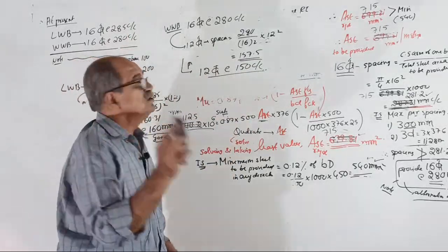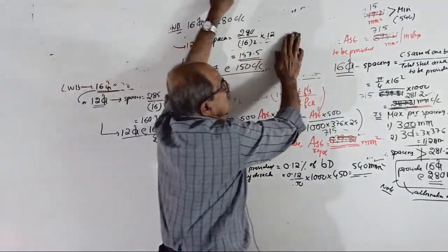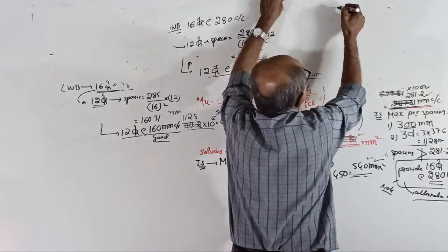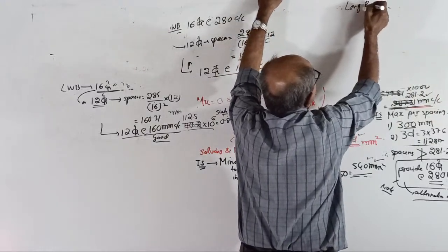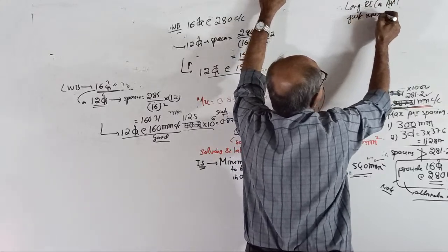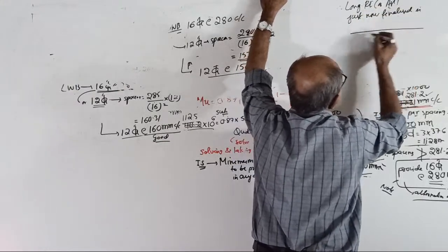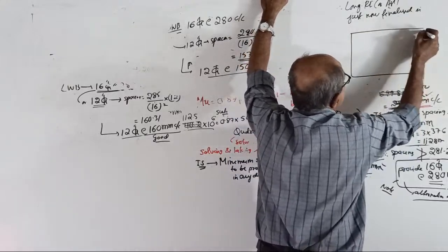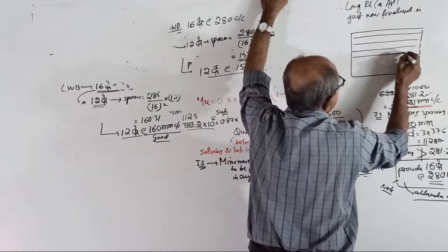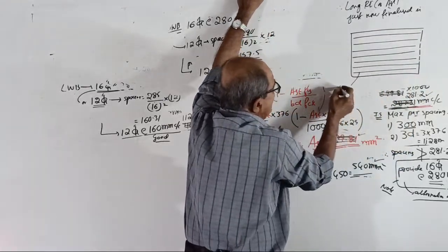Now make a final note. Very important. I will write it somewhere here because I need it later; I will not explain again. Therefore, the longitudinal reinforcement, or AST, just now finalized, is for lengthwise bending. This is the lengthwise bending steel. This way. Don't count the number of bars, it is out of scale. This is the steel, AST, for